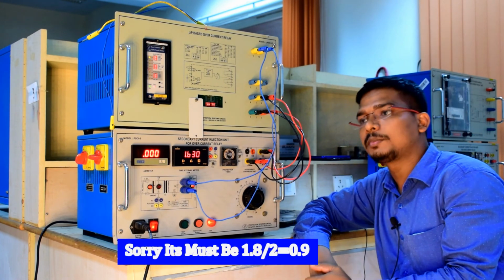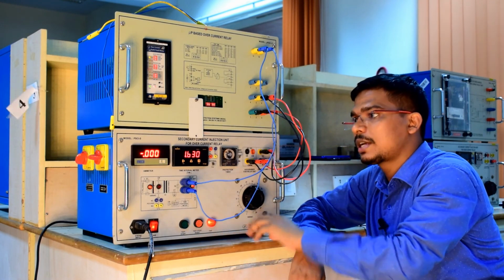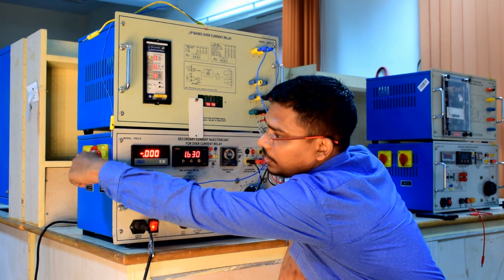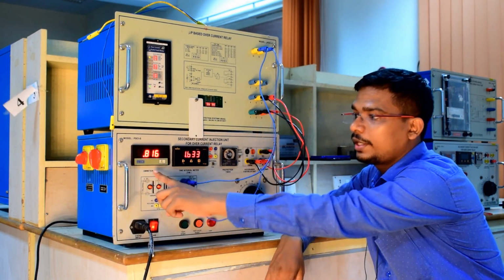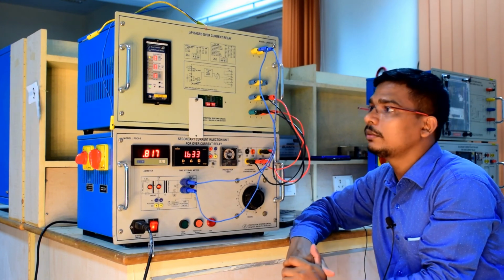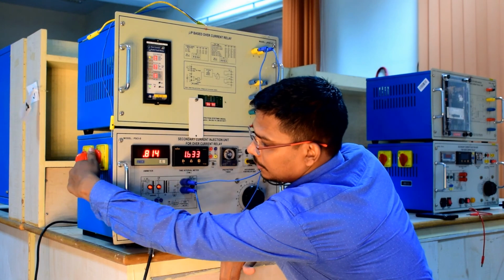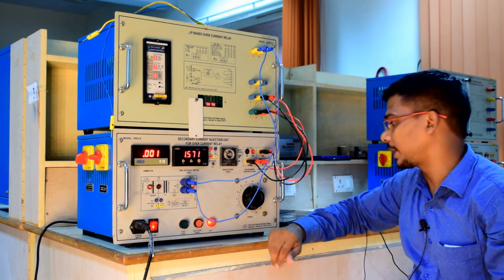So we just have to see 0.8 here. Already we have position 0.75, so directly we can reset, change the position to 1 and start this, and 0.8 you have applied. Now it should go to trip when we change the position of the rotary switch to 2. So this is going to trip,